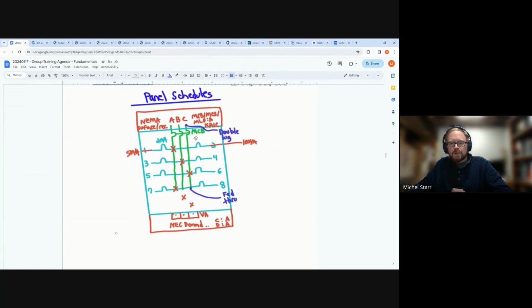There's a couple different exceptions to the ways you could do that, but mostly there's going to be a circuit breaker, and it's going to be within 10 feet of the terminals of the transformer, for the reason that that's a tap, and so it needs to have overcurrent protection and not go so far. The code doesn't want you to go too far before protecting.